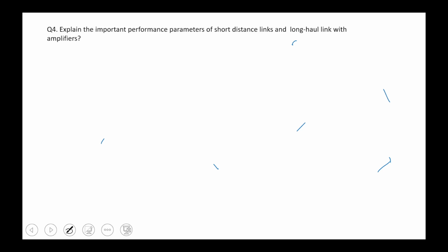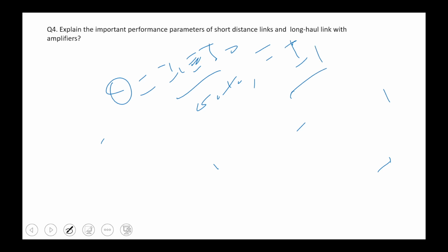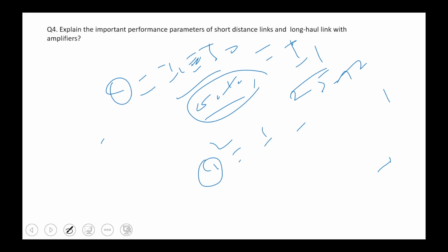No, sir, no. So, Jagannath, we already said that we defined the quality factor as I1 minus I0 upon sigma 0 plus sigma 1. We can rewrite it as I1 upon 2 sigma t, the average of Q1 and Q0. So Q square we have defined by squaring everything: I1 square upon 4 sigma t square. Sigma t is the total transmitted standard deviation.